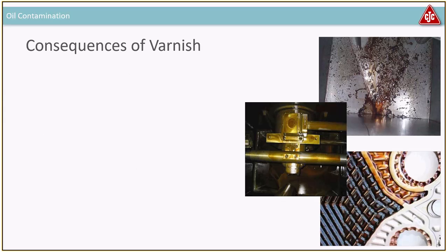I'll show you these instead. This is how varnish looks in a hydraulic system. This is looking into the oil sump, and here they just pulled the plug, and you can see there's a lot of varnish and particles sticking here. If I don't remove that, my new oil will dissolve this back into solution, and then I'll be pumping it around in my system.